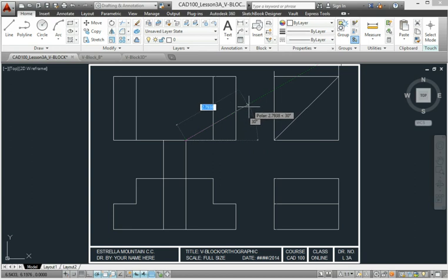In order to use this, there's two things you could do. You could click beyond it and trim it off, or you can pass the line in which you're drawing and look for the intersection of the line that's already on your screen and the polar tracking line and pick that. Just, however, don't pick the midpoint. That's not the correct line. So we'll do it both ways.